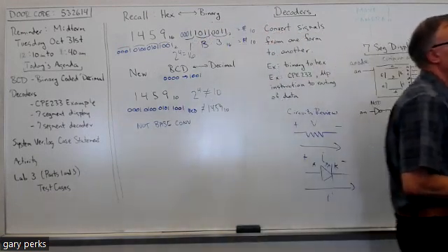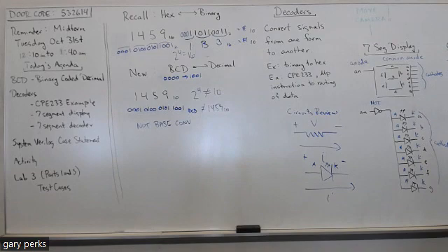So in order for one of these LEDs to light, and remember, in a digital circuit like this, we only have two possible values, right? A 1 or a 0, where a 0 represents 0 volts and a 1 represents some plus amount of voltage, like 5 volts. Well, in order for an LED to light, we want this common anode to be a 1. Okay, because that would be some plus amount of voltage, say like plus 5 volts or plus 3.3 volts.